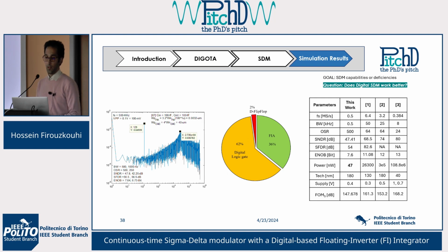According to this table, you can see that the power consumption is significantly more efficient, in the range of nano-Watts, compared to other sigma delta modulators, and the FOM is not so good compared to other state-of-the-art results, but it makes this concept suitable for IoT nodes, since we need ultra low power, smaller size, and more importantly, a digitally implemented concept. This is the preliminary result,